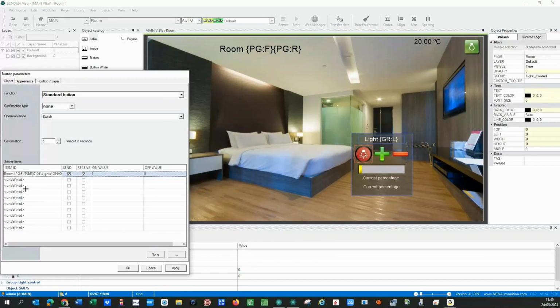So if you know the syntax, you can also substitute this variable. Okay, so we have to select the floor, we select the room, we give values to the floor and the room, and we will give also value in terms of selecting which is the light to control as a third and next dimension of the variables. So selecting the room and also which of the lights in the room you want to control with only one widget. We have 6 lights, 8 rooms, 48 lights that can be controlled with only one widget design.